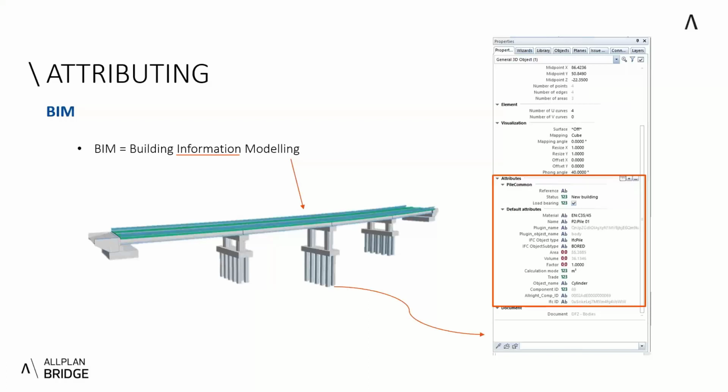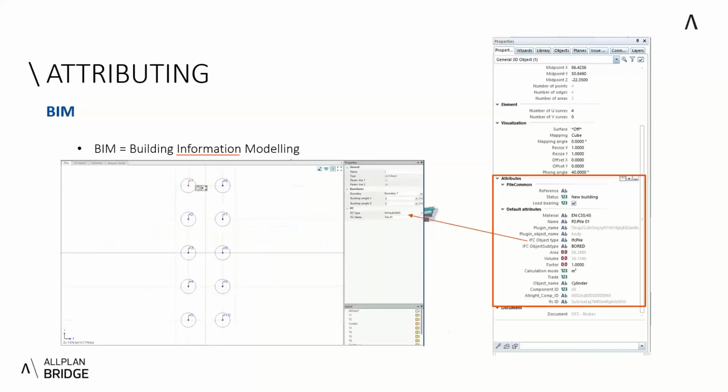Of course, you could assign the attributes from BIM Bridge directly. So this is BIM Bridge, where we were creating the cross sections. While you are creating the cross section, you can assign the FC type. You could also add materials in the girders. So you can do different assigning of attributes in BIM Bridge.